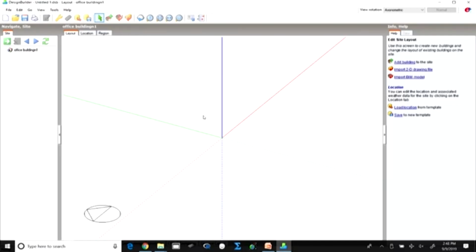Another important thing that we have to do is clean our DWG files, the drawing files, because a lot of details which are usually added in drawing files are not required for creating the geometries in whole building simulation tools. So, here the DXF should only have the basic information as far as its walls and openings are concerned.